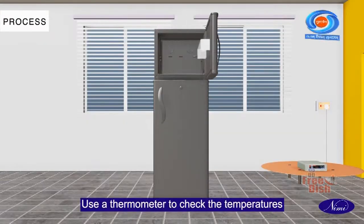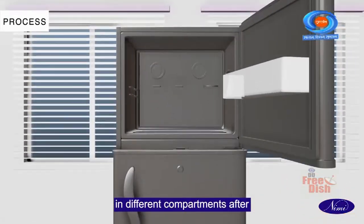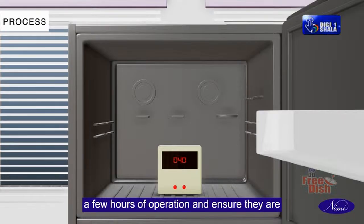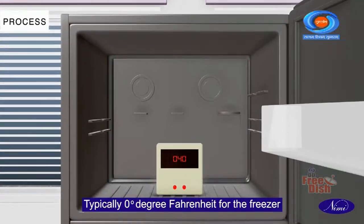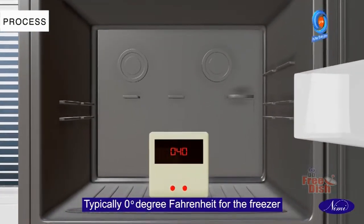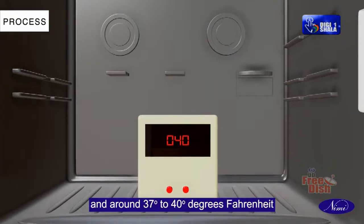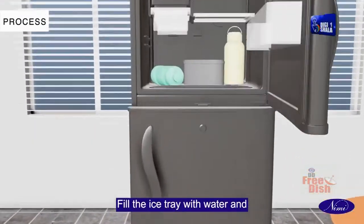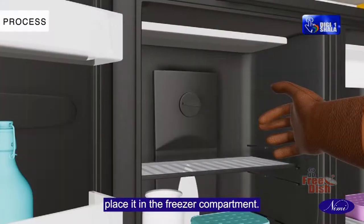Use a thermometer to check the temperatures in different compartments after a few hours of operation and ensure they are within the recommended range. Typically 0 degrees Fahrenheit for the freezer and around 37 to 40 degrees Fahrenheit for the fresh food section. Fill the ice tray with water and place it in the freezer compartment.